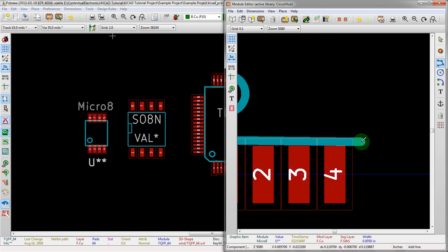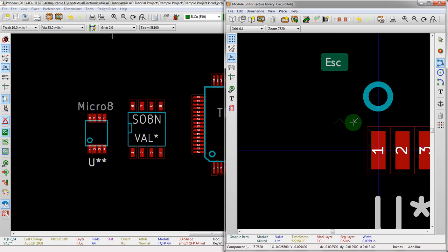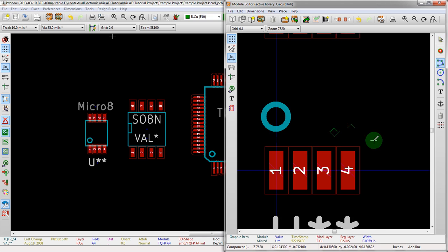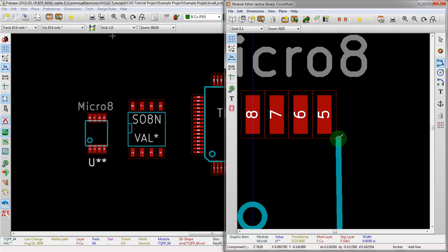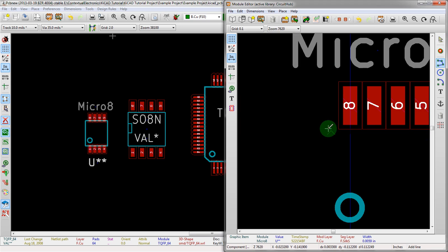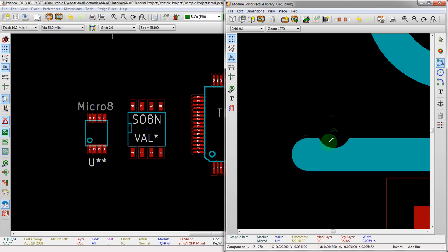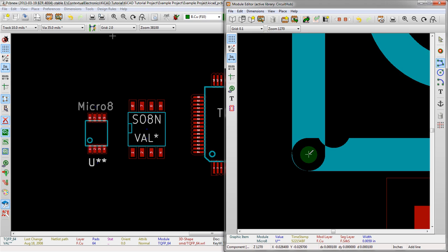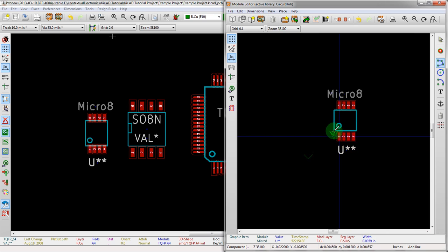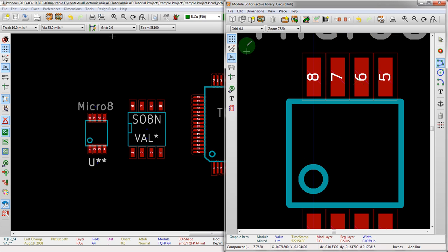All right. Oh, didn't reference it out. Yeah, that's much better. And we can just approximate this with the silkscreen, it's not nearly as important as the actual pad, so that is a nice thing. Main thing here is trying to get straight lines. That's the main thing. Otherwise it looks a little wonky. And there we go. That's much better. Okay. So we'll save this.